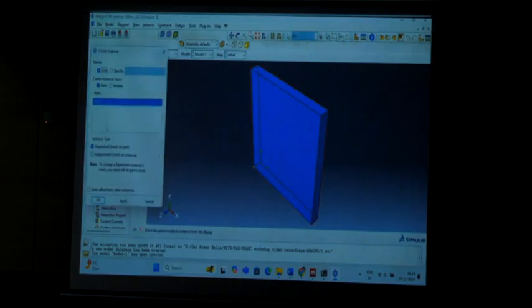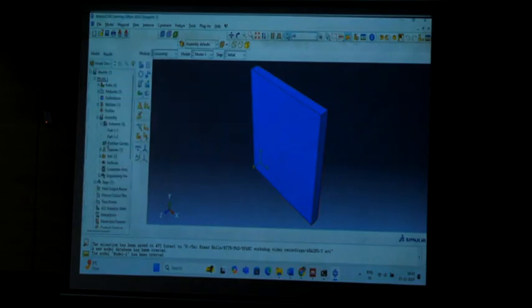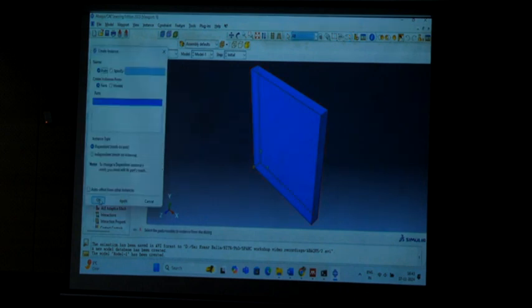And one more time, suppose we are going to check for 3 options, I mean 3 layers. Again we will click on this, and this will be dependent on each material, I mean you have to choose the instance type as dependent, because each layer will be dependent on an already deposited layer. In that case, one more time click OK. So here we have seen part 1, 2, one more time, because 3 layers.